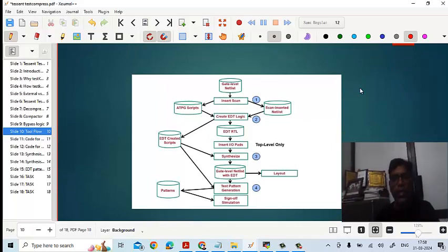This is more important because this is how we are going to do this task. This task is a bit lengthy because we are going to shift over from Tessent to Synopsys DC compiler and back to Tessent. It's a bit lengthy, but the procedure is pretty simple. You first take a netlist. As far as our task is concerned, we are going to use netlist.v, which is the CPU netlist.v. So here we have this under the name netlist.v.